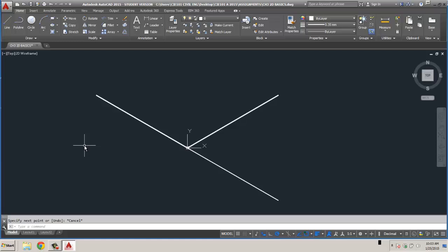Now let's look at some Cartesian coordinates with a line. We'll start again at 0, 0. And we'll make this line 10. Now, instead of hitting the tab key, I'm going to hit the comma key. And when I hit the comma key, it puts me in XY coordinates. So you can see there's 0, there's 10 and 0. And if I pull it up, it's locked at 10. It's 5 up. So it's going 10, 5.